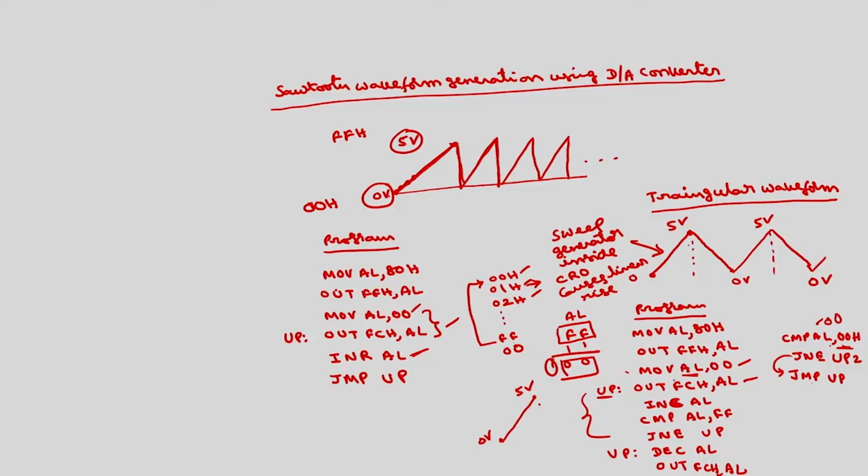So, we will go to here again from 0 onwards. 0 will be displayed, then 1, okay, like that it will display up to 5 volts again. So, this loop will change from 5 volts to 0 volts. So, like that we will get the triangular waveform.